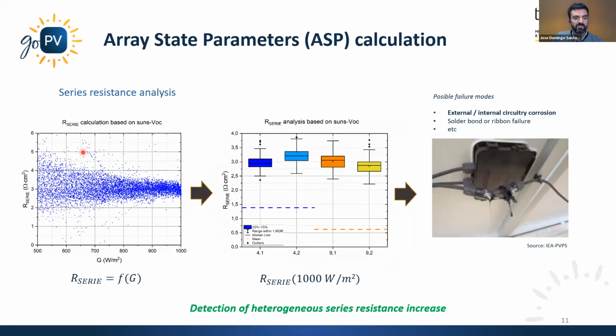The combined information of the open circuit voltage and the maximum power point voltage also makes it possible to carry out an estimation of the series resistance of the PV array. Specifically, a series resistance greater than that obtained from the PV module characteristics is obtained.